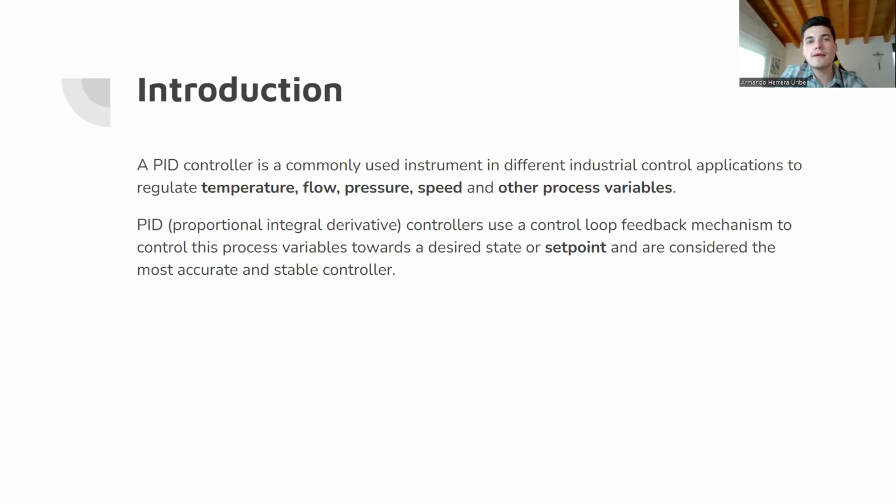This set point is usually given by the user of the system, and it's like an ideal state, or where the system should be working to achieve a desired result. And this is why the PID controller is thought of as the most accurate and stable controller. It is important to mention that this type of controller is recommended for systems where the load changes often and the controller is expected to compensate for these changes automatically, or when the set point can change throughout a given period of time.